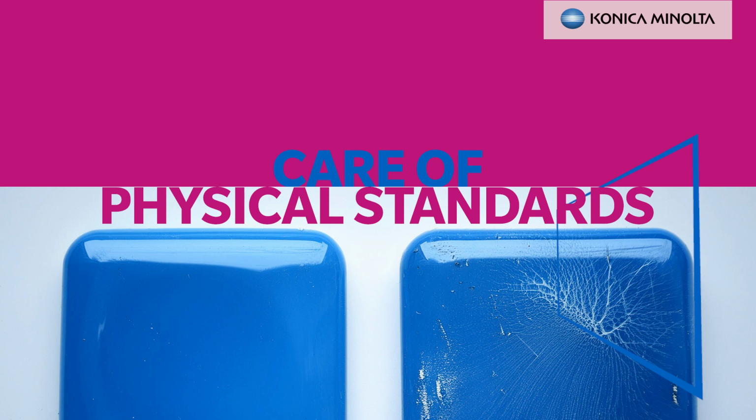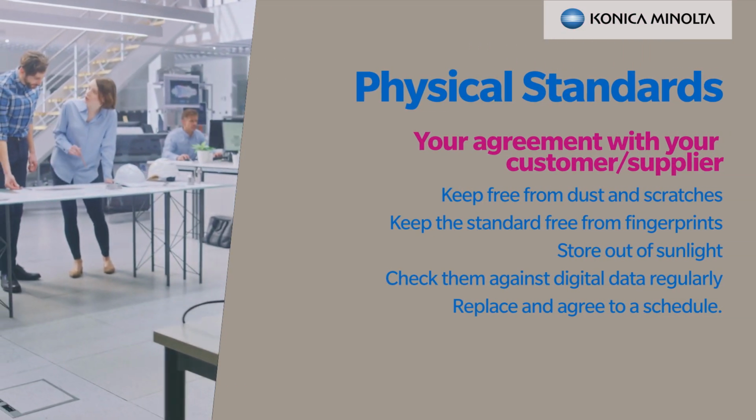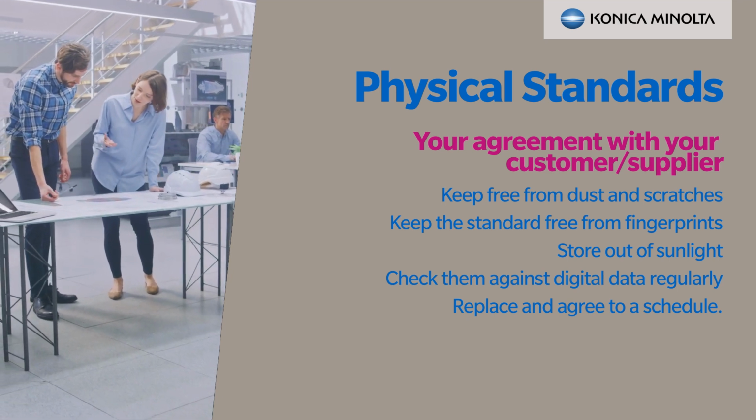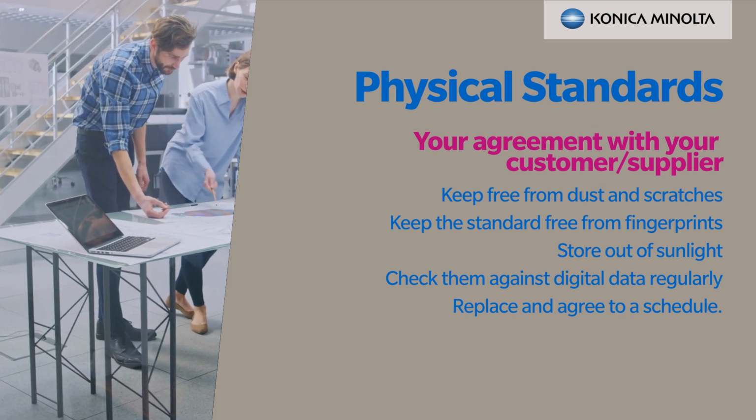If you're maintaining a set of physical standards, you should take pains to ensure they're protected. Physical samples should be free from dust and scratches. They should be carefully handled, avoiding fingerprints on the surfaces that you need to measure or assess visually. When not in use, they should be stored securely out of the light. Even small, gradual changes will eventually lead to a large deviation from the originally agreed target and can cause rejects. You should routinely check your master and working standards with a calibrated measuring instrument to validate their accuracy and acceptance to specification.